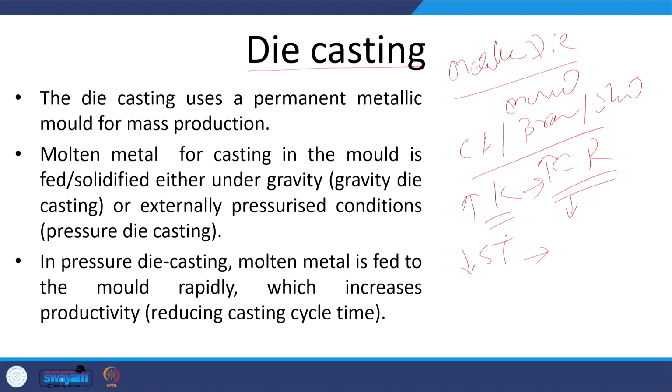Reduced solidification time means less time for escaping of the gases and inclusions. So, there is a possibility that the entrapment tendency of gas and inclusions will be more due to the lesser solidification time.